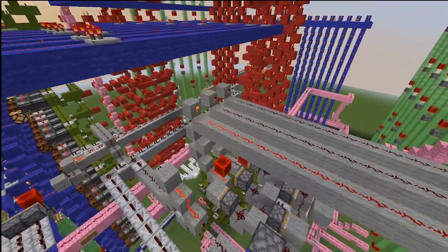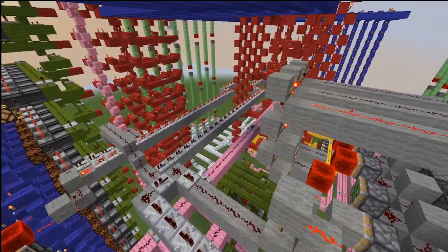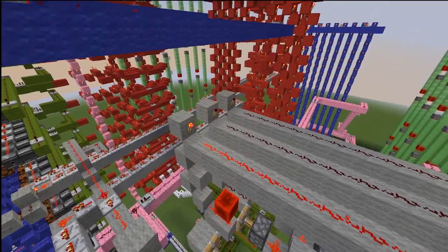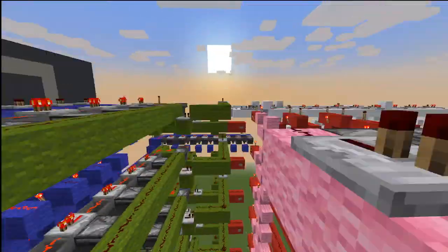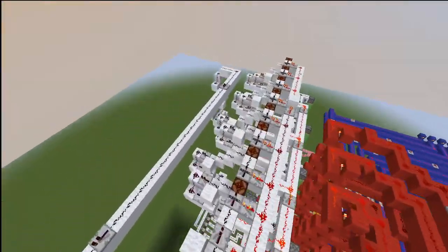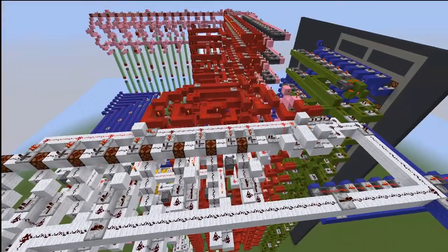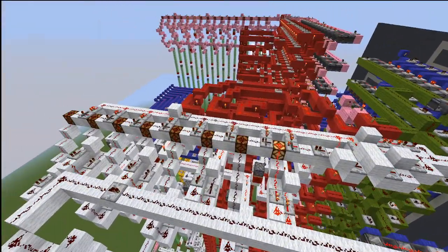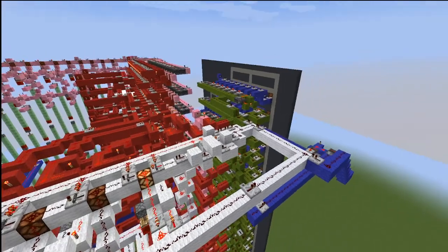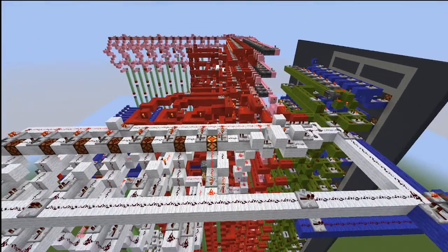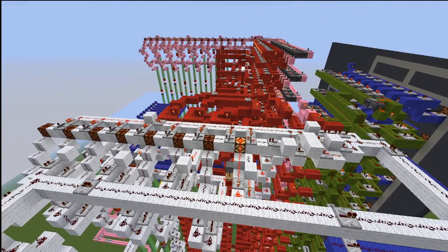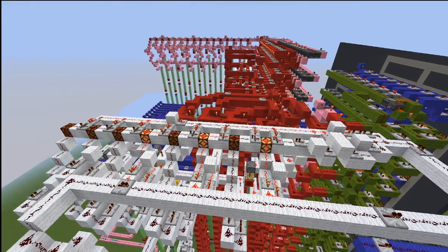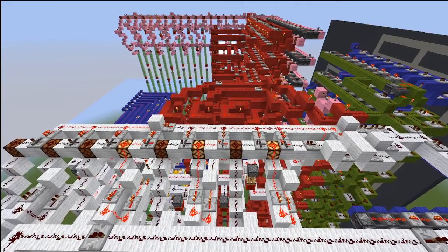Anyway, on this next clock pulse, when this cycles back around, we'll start the macro instruction for load the accumulator. And there it goes. So if we come back over to this address and data bus here, it's going to read from the program counter, which since it incremented, it's now going to read a 1. And there it is. And now it's going to select line 1 from the memory address register and take that out of prom. And here that comes. So this is what it loaded.